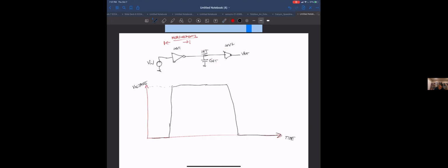In our case this is 1.8 volts. Normally it'd just be VDD, whatever the supply is. If this was a 65 nanometer process, we'd be using a 1 volt VDD. But in this particular case, it's a 180 nanometer process, and we're using a 1.8 volt VDD. That will stay with us for the rest of the projects.